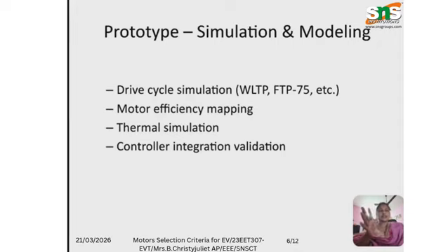Once we select the motor based on the available options, we move to the prototype stage. Here we don't directly build the motor. We first test it using simulations like drive cycle simulations, wherein we impose real driving conditions, and efficiency mapping, then thermal simulations like heat analysis, and also controller integration validation. This helps us avoid mistakes before actual production.